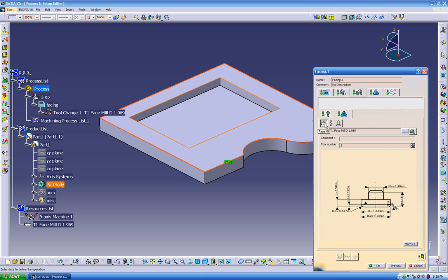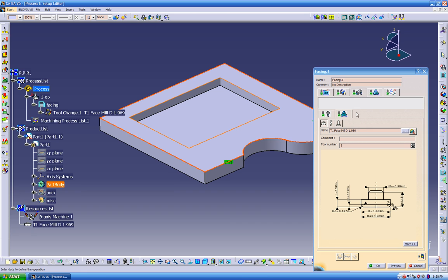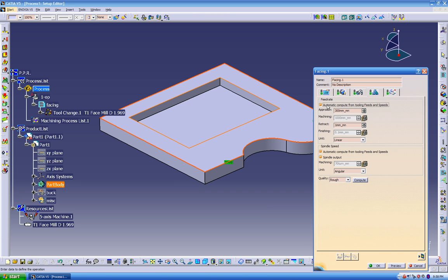And let's choose a face mill, and you can change the diameter: 2 inches, 3 inches, whatever the CNC shop has. Feeds and speeds, come over here. This is the RPM. So for a 2-inch face end mill, I usually go on aluminum at 3500 RPM,